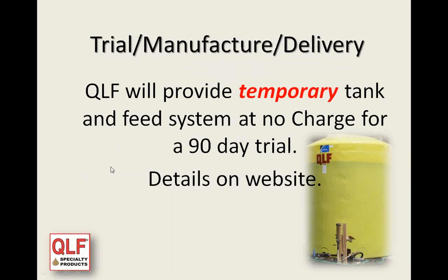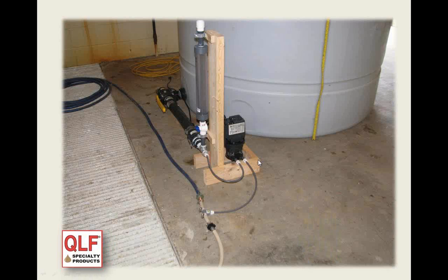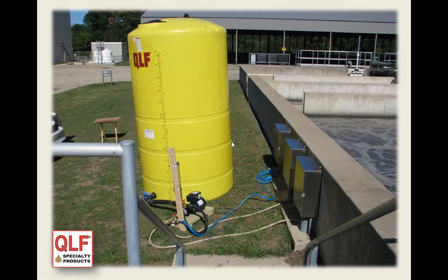QLF will provide a temporary tank and feed system at no charge for a 30-day trial. There's details on our website for that. Here's a picture of one of the temporary setups. We have a tank, use a peristaltic pump in this setup, a calibration tube, and it's directly off the line. We use carrier water. We pump the product into carrier water, and that's discharged, in this case, right into the anaerobic zone. This is when we were at Fort Atkinson, and here we were using a progressive cavity pump.